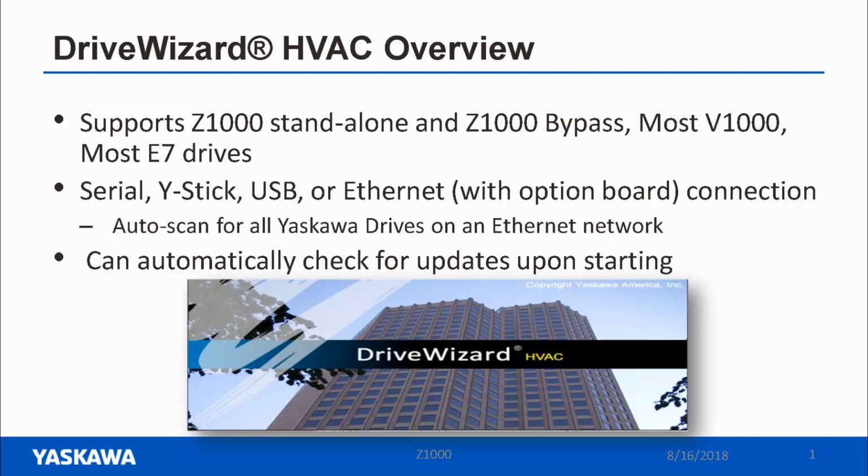So let's get into the PowerPoint here. As I mentioned, it supports Z1000 standalone and Z1000 bypass, most V1000, and most E7 drives. There are several ways to connect: the serial, you can use the Yaskawa Y-stick, you can use a USB cable, standard printer cable, or the Ethernet connection, provided you have the optional board. DriveWizard will automatically check for updates upon starting.